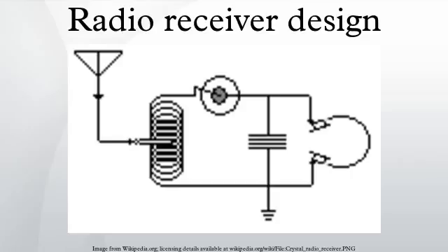Superheterodyne. Practically all modern receivers are of the superheterodyne design. The RF signal from the antenna may have one stage of amplification to improve the receiver's noise figure, although at lower frequencies this is typically omitted. The RF signal enters a mixer, along with the output of the local oscillator, in order to produce a so-called intermediate frequency signal. The local oscillator is tuned to a frequency somewhat higher than the intended reception frequency so that the IF signal will be at a particular frequency where it is further amplified in a narrow-band multistage amplifier.